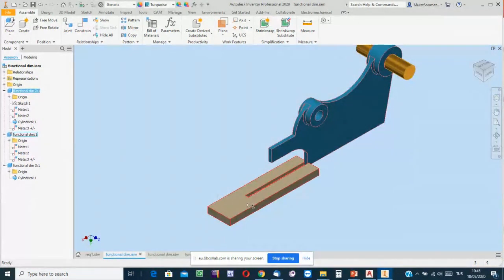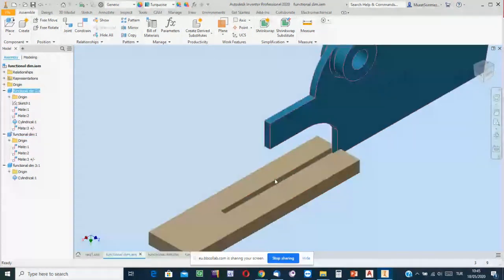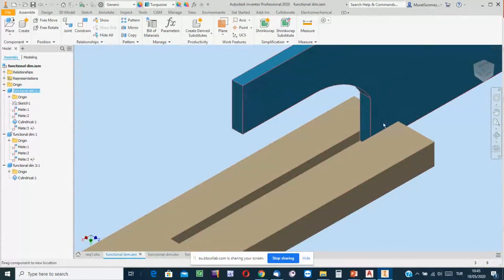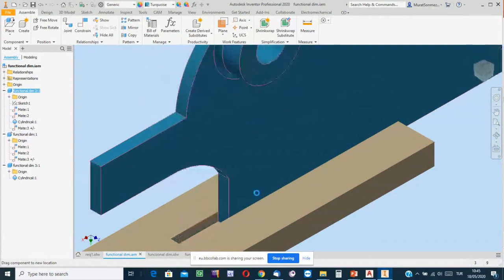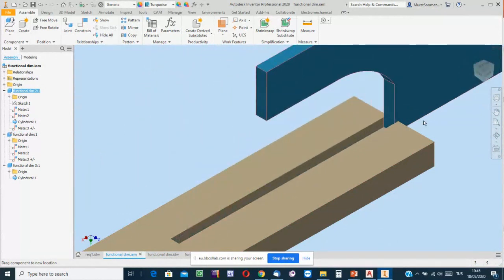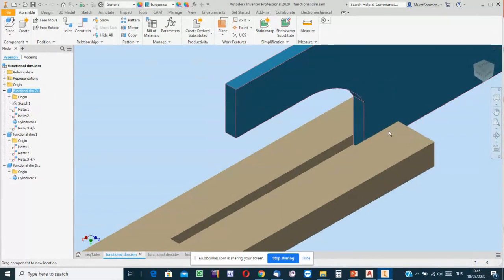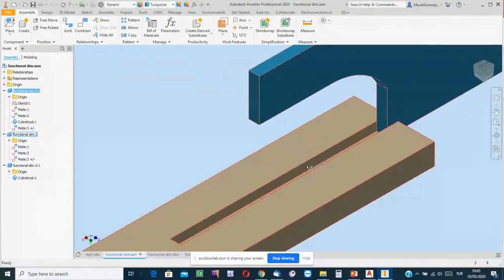It is a feature in the design of the other component. So, to be able to have the clearance between the features of the components in the correct order, we need to determine the size of the features more precisely using smaller allowances, smaller tolerance. You know the definition.